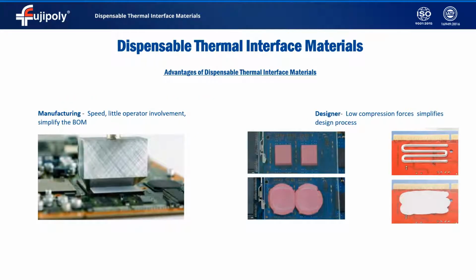There are both manufacturing and design factors which influence the decision to use dispensable thermal interface materials. Automated manufacturing is highlighted more than ever with employee shortages we have experienced within the past 2 years. While solid gap filler pads can be placed robotically, it can be challenging to design these systems to pick the materials consistently and in a timely fashion. Dispensable systems, on the other hand, have been commonly found in large manufacturing facilities for a long time. They are commonly used for coatings and adhesives, but the same robotic systems can typically be used for dispensing thermal interface material.